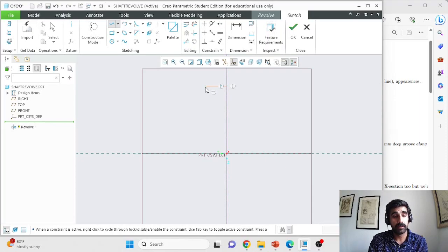You might have noticed that Creo helps me create horizontal lines whenever there is a standard orientation, horizontal, vertical, or at a particular angle. It snaps over there and makes it easier for me to make lines in those orientations. But now when I pull out, line chain still gives me the option of making additional segments. And this will continue until I tell line chain to stop. I can tell it to stop either by hitting escape on my keyboard or by pressing the center mouse button.